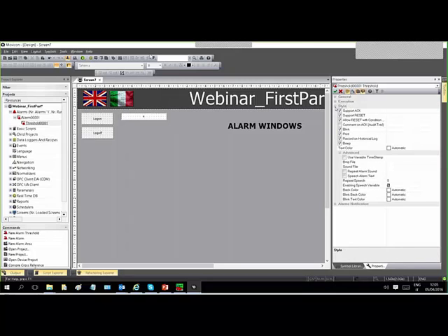And you can go in the threshold and modify the style. The style is important because in the style option, you could allow the operator interface. It means support for the acknowledge and the reset. Look, this is an alarm. If I remove this operator interface, look, it's no longer an alarm. It's for us a message in the alarm banner. You will find the same symbol in the alarm window.